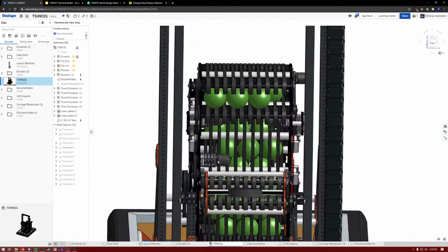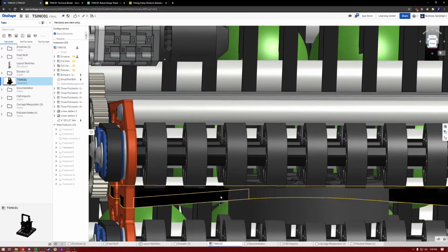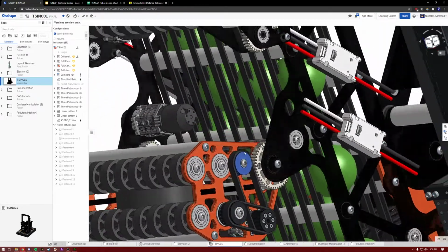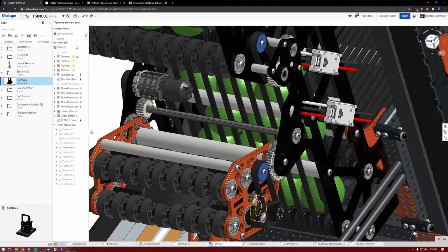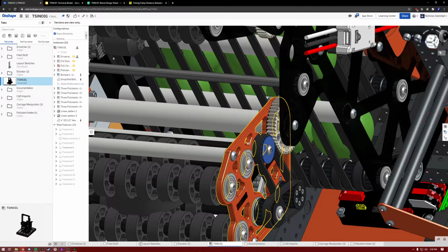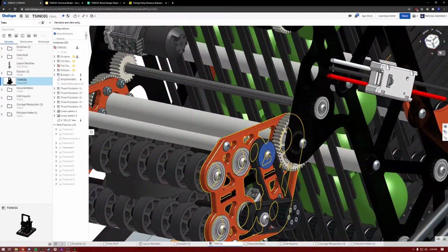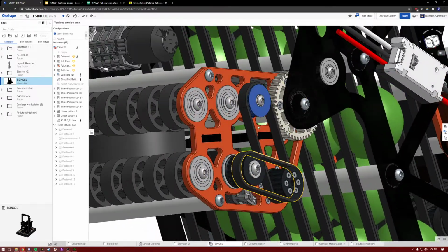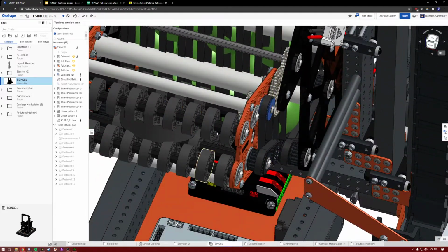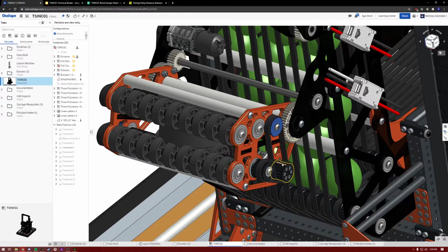The scrubber claw, like I said, has this self-centering thing right here. It has something that you'll notice throughout this entire robot if you dig into it, which is this gear reversal right here. Basically, I didn't want to use more than one motor, but I did want these to run in opposite directions. You can do that a couple of ways.